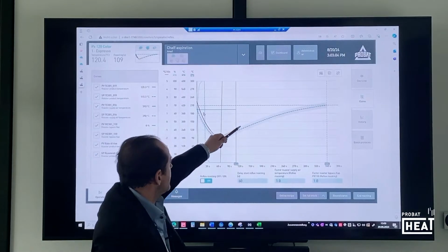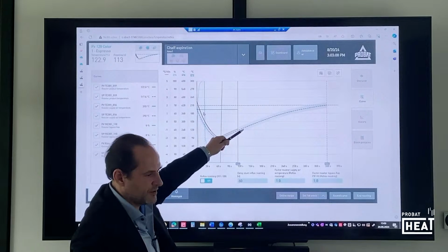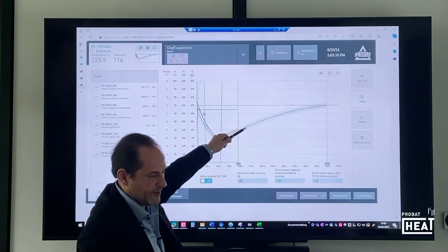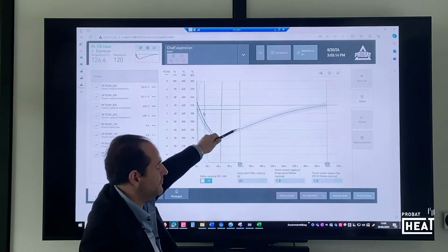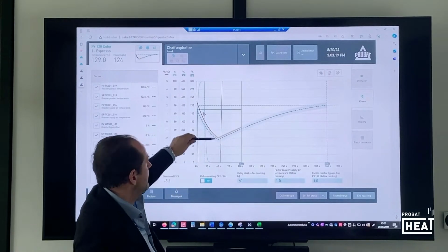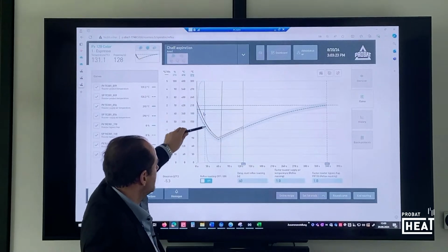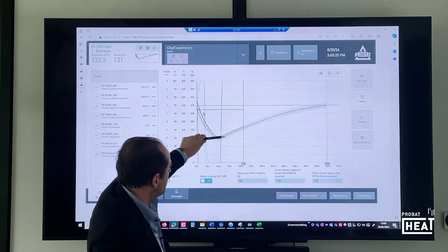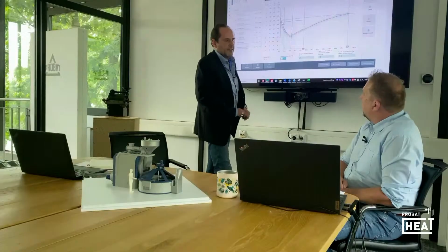This means we have here this gray area. Yes. And this means the range. This means this is deviation. We are able to set it up in the recipe, I guess. Yes. And as soon as we are within this range, we have a yellow color. This is a kind of warning, in my understanding. Yes, that's right. And if we are outside this one, we have here the red marked line. And our target is the dotted line, so that we want to hit the temperature. Is this correct? This is correct.